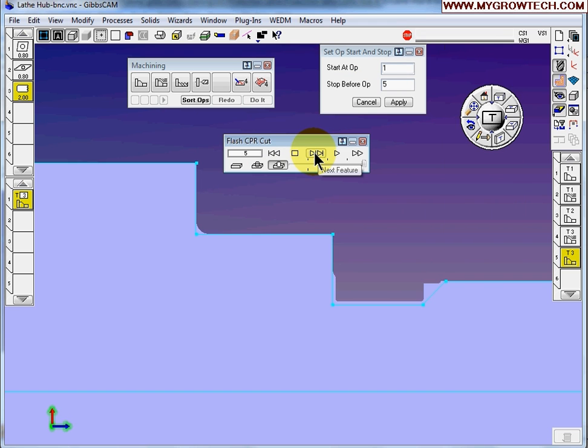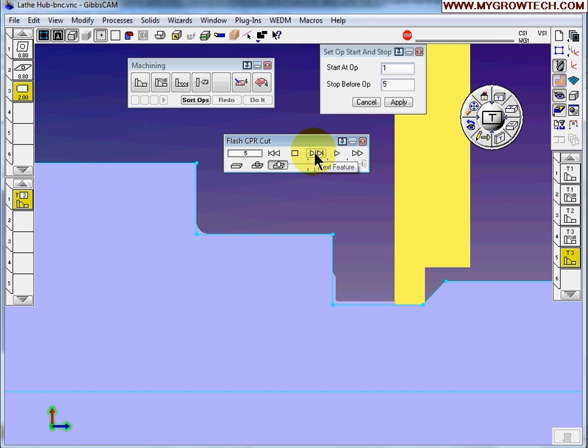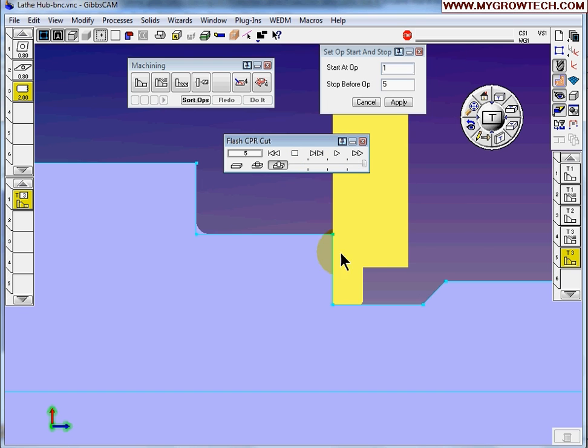This is how the finishing groove cutter will cut. You can see here the cutter is dragging when the tool is moving up. This is bad for the groove cutter. It might break it. Yeah, the tool might be broken.